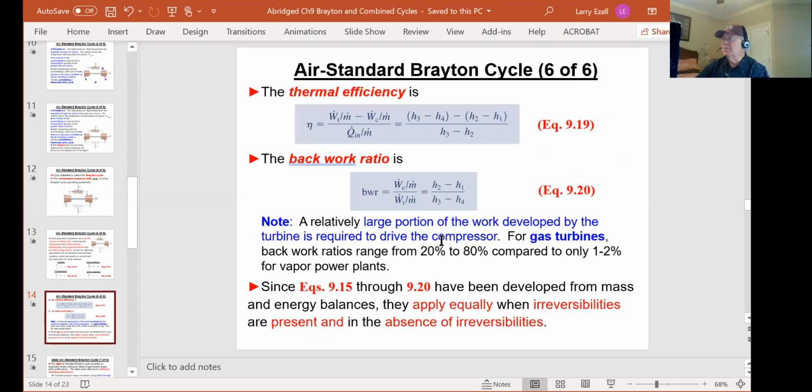So if we look at the thermal efficiency, that's the net work, net, N-E-T, work, 2 words, not "network" like you know what I mean. The net work over the energy in. And you can write the M dot times the H's, but regardless how you write it, the M dots will cancel out and you're left with these 2 enthalpies.